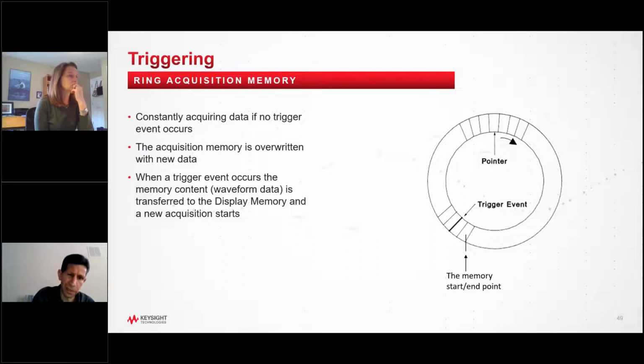So you have 50% pre-trigger, 50% post-trigger. So again, that's an important point. Real-time scopes do this, sampling scopes do not. With sampling scopes, the trigger is always in the center. If there is no trigger, there's no data, nothing is overwritten. And then as soon as that trigger occurs, we delay by very small increments on successive triggers and fill the waveform memory.